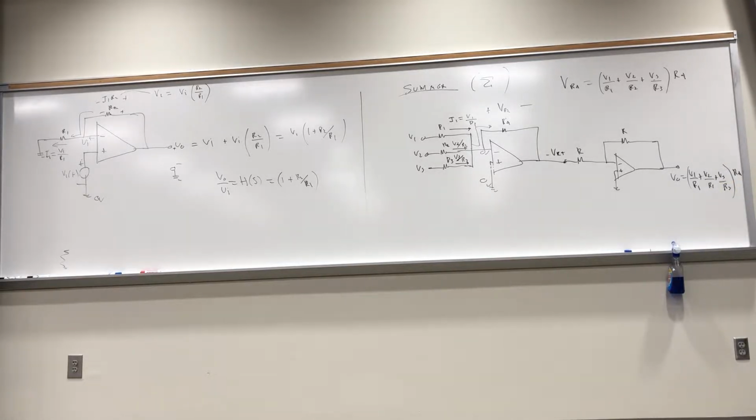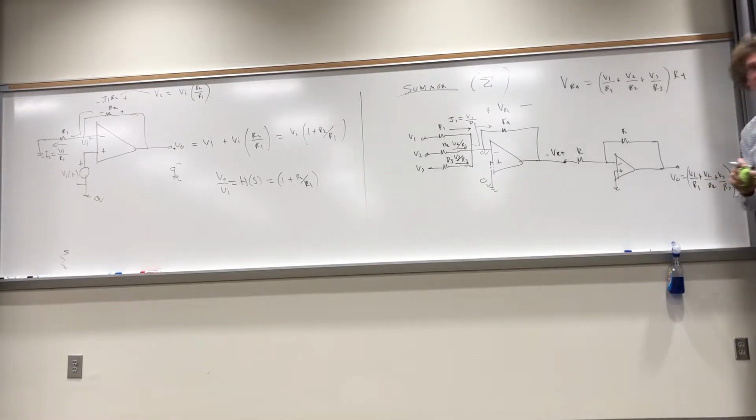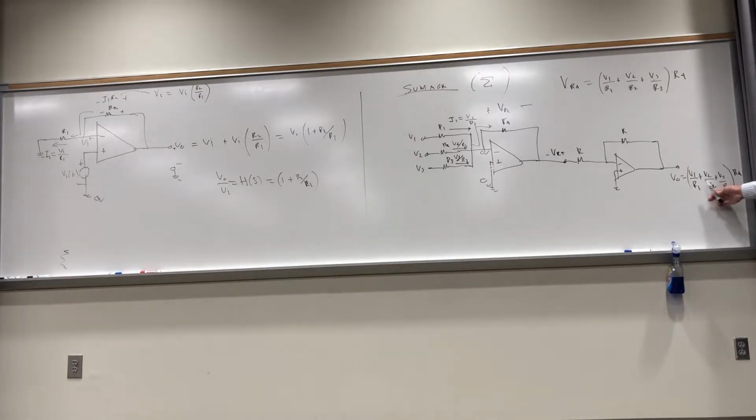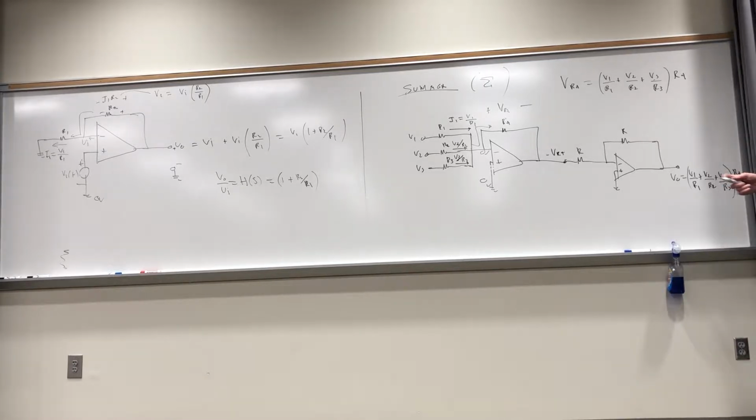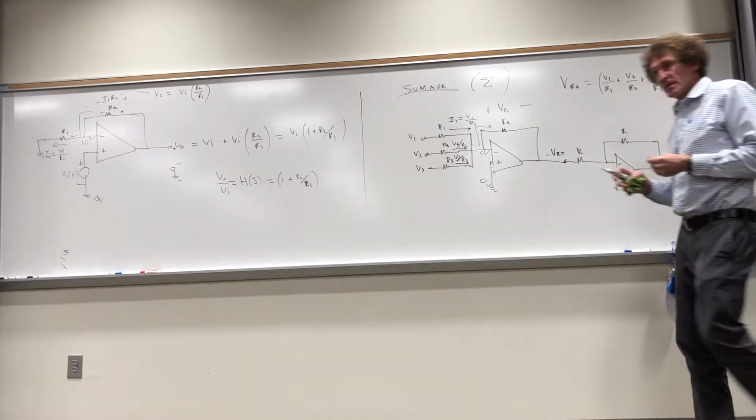Now I want you to take one look at this for a second. How many see this first of all? Y'all see it in the back or not? What if I make R1, R2, R3, and R4 all equal to the same value, or 1 for that matter? What does that become? It sums up the voltages, right? It just adds them up. Now listen, I can also get any effect if I want. If I want just V1 by itself, I could have R4 over R1 equal to 1, plus 2V2, then I could have R4 over R2 set to 2, plus 3V3 added up to the output. Follow me? Now I can proportionally weigh these, so I can do that as well.